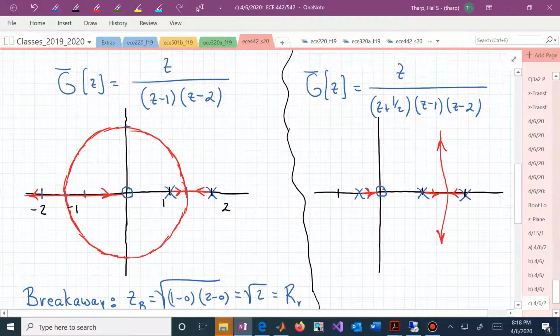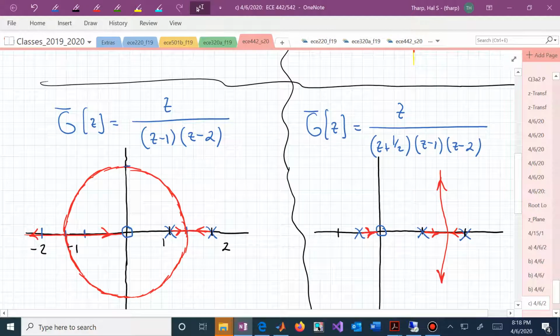What about the next root locus? Now we have two poles, one at 2, one at 1. The line segment between 1 and 2 has an angle of 180 degrees. And there are two branches of the root locus, one branch here and another branch there. Suppose we say the blue branch now leaves. It can't stay fixed, and the yellow branch goes in the opposite direction.